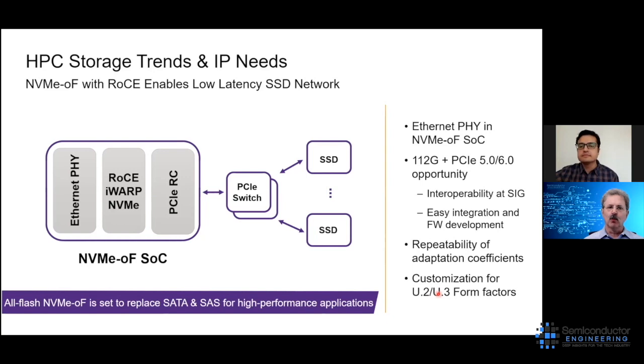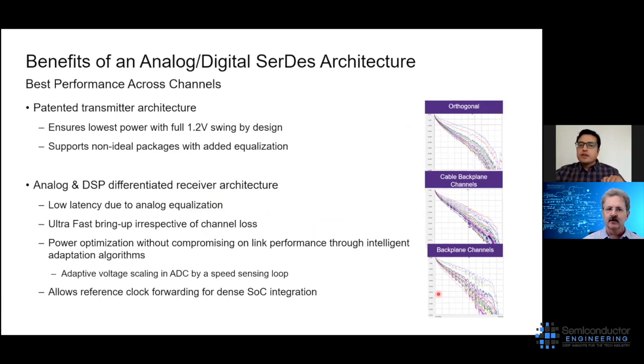So given all of this, what happens on the SerDes architecture itself? How is this changing? So now is the time where you need a SerDes that does this equalization by balancing analog as well as digital signal processing. Analog and digital signal processing both offer excellent merits, but it's very important that these are balanced. If digital signal processing is the only implementation option, you run into a lot of latency issues, and the performance and implementation doesn't become a competitive implementation.